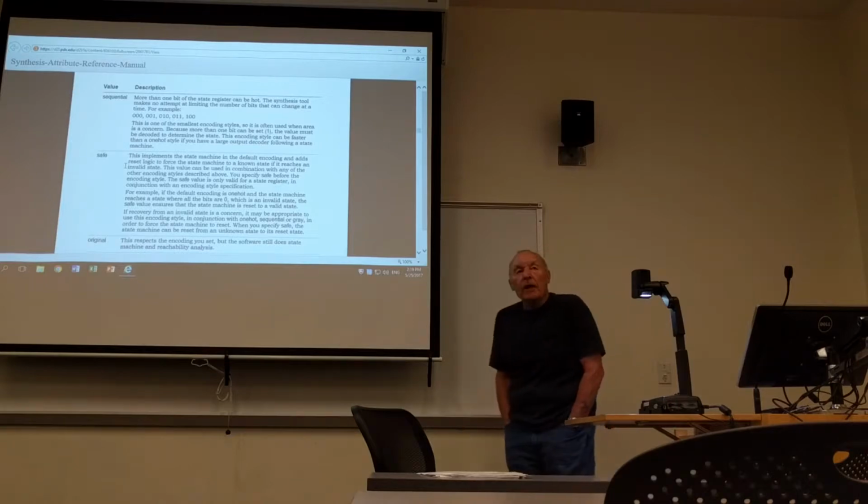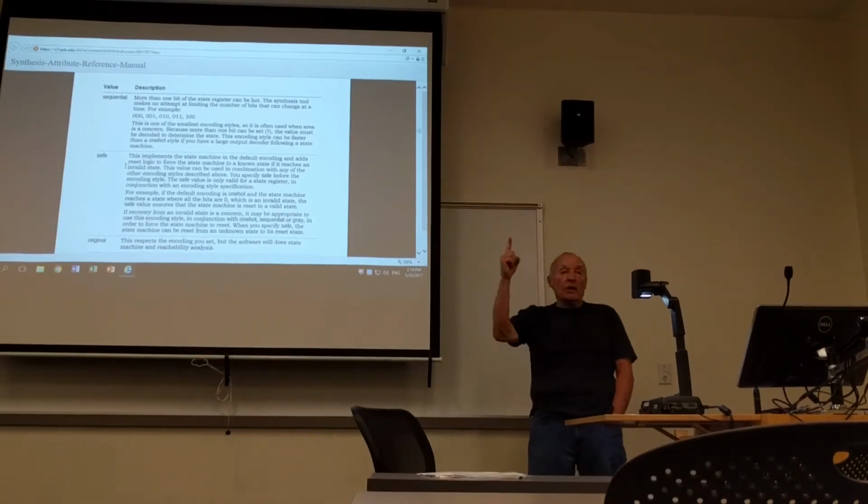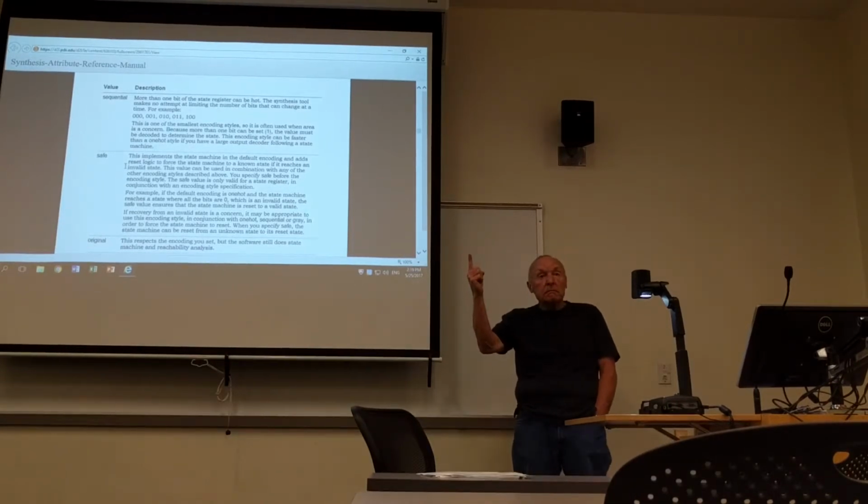You recall on a finite state machine you have at least one input, other than clock not being considered an input. That input may be coming from the external world. And so it is not synced in any way to your clock. What happens if that input comes in and does not satisfy the setup time before you get a clock?